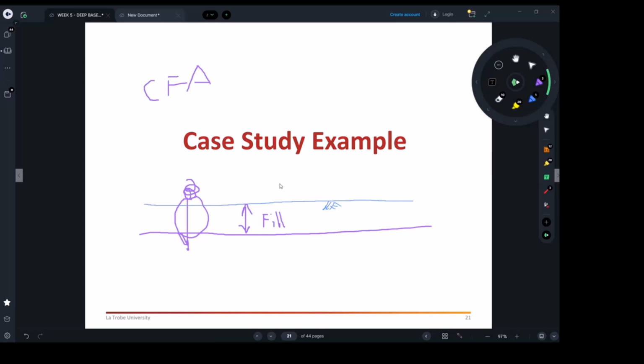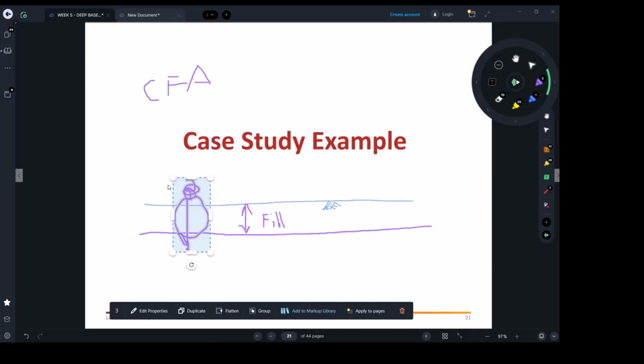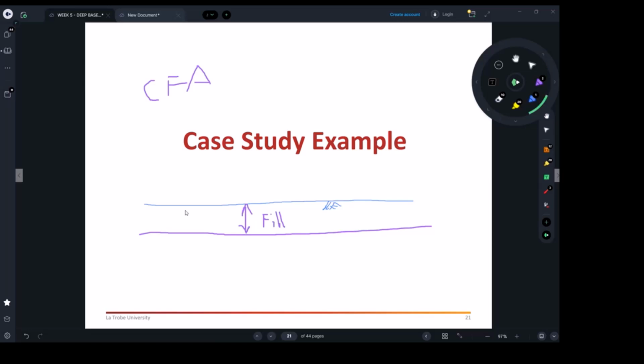And if you got a fill or a sandy soil, it will always collapse. So what we do, we try to use the drilling bucket, which is about 1 meter diameter. It will help us to, so if I clean this now, it will help you to go 1 meter decent excavation or even deeper. You can take it as much as you want to give you a large room.